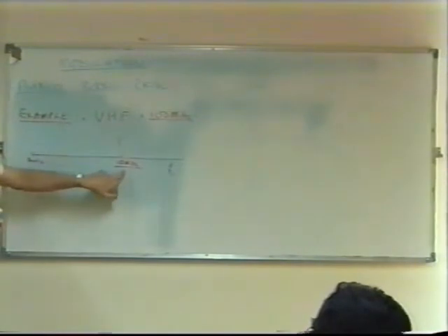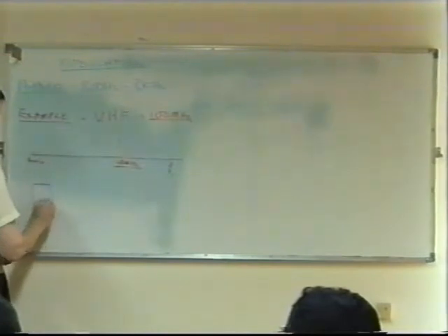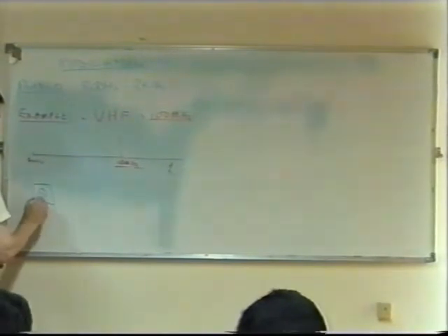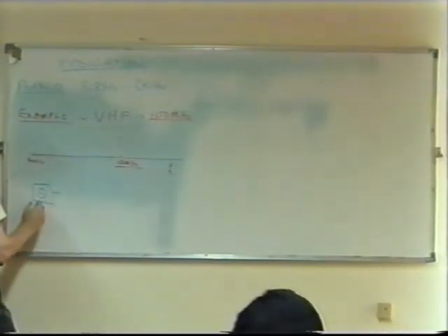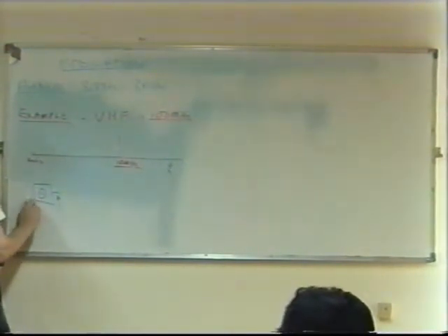So, if you think about if you were to design a simple radio system, the very first thing you would need in your radio is some sort of generator that can generate 100 megahertz. Okay? An oscillator, in other words. So let's just draw that in our simple case. The first little block here would be some type of oscillator, probably using a tuned circuit. Could be using a crystal, as we'll see later, but it doesn't really matter. The main thing is it generates our frequency, let's say 100 megahertz. So the output of here is 100 megahertz. This is our oscillator.